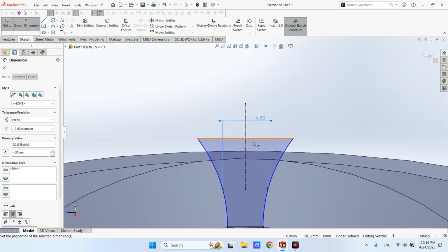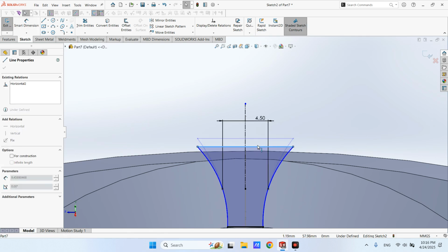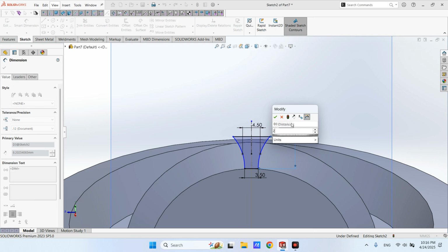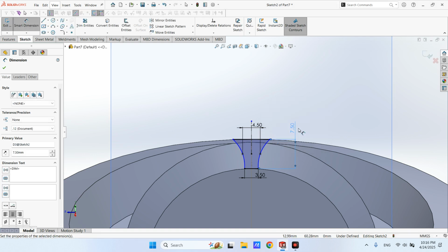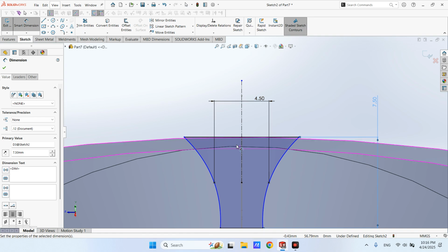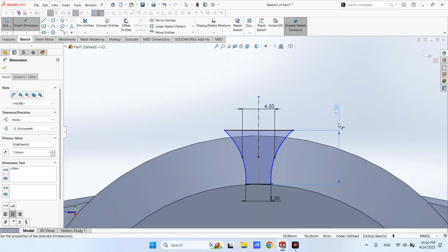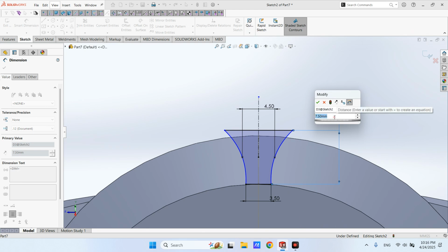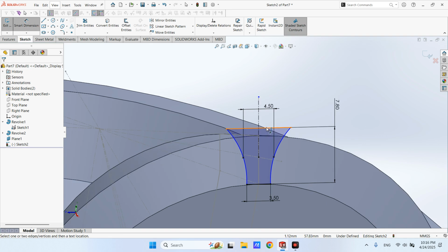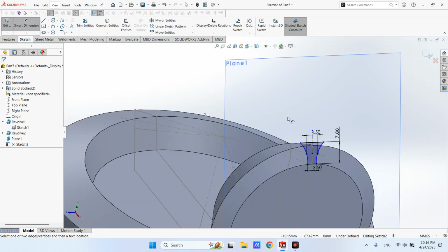Let me get normal again. You can change your dimensions somewhat. It's better to define this dimension also. This dimension is 2.5 multiplied by our module, which is 3, as you can see. Okay, as you can see, it's almost tangent to the top of the sketch. To avoid any difficulties, I add another one. For example, I add 2.6 multiplied by 3 so that I will make sure that this line will always be out of my model.